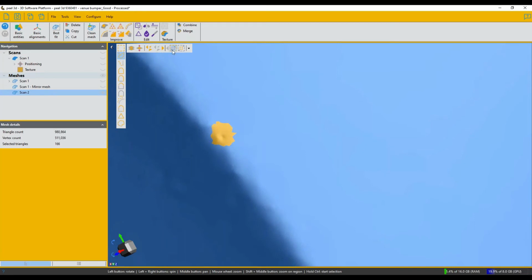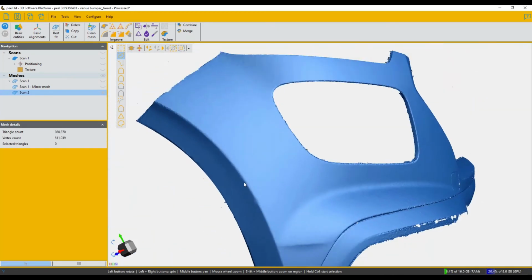As a best practice, I always recommend increasing your selection area once or twice. That's going to help select any triangles that were hidden on the interior that you can't see. There might be a cavity or something, so you want to increase your selection area to make sure everything on the interior is selected. And then if you want, you can back off your selection again and then use the de-feature tool, and that's going to basically rebuild the mesh within that localized selection and get rid of that unsightly feature that may hamper the flattening process.